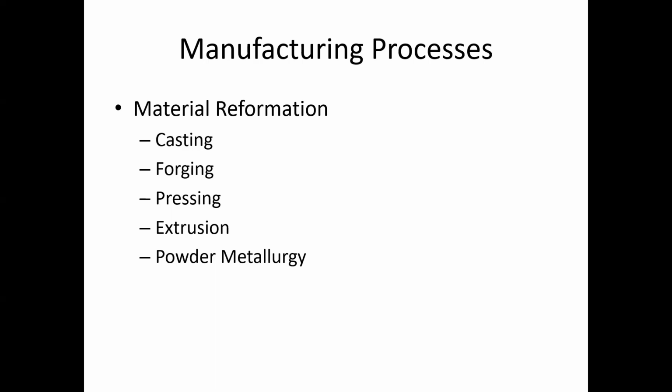What about forging? Who knows what forging is? Heating up a piece of material and kind of pressing and stretching it. Yeah, so that's true. You heat the material, and then you deform it, you change the shape with force and pressure. Right? A lot of times that could be as simple as a blacksmith hammer, or it could be as complex as a 50-ton hydraulic press or 500-ton hydraulic press, depending on the size.